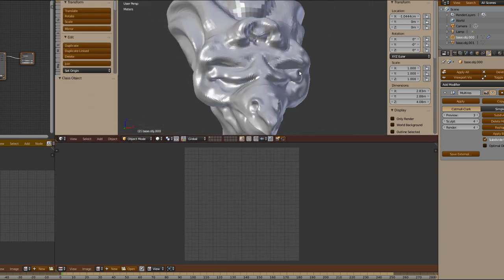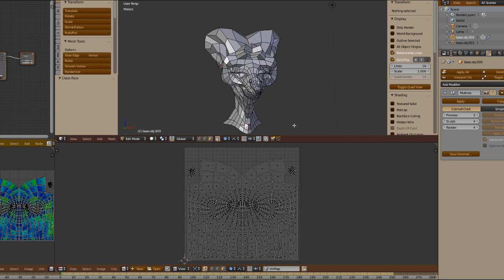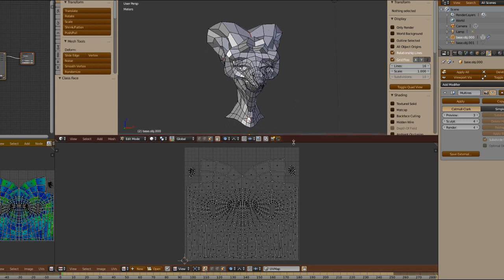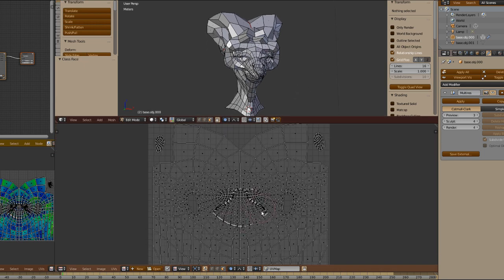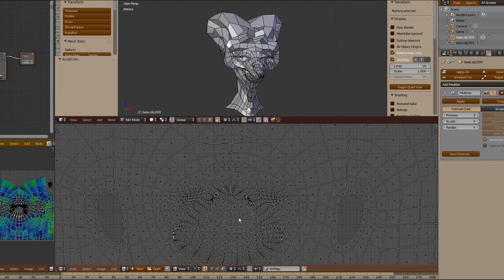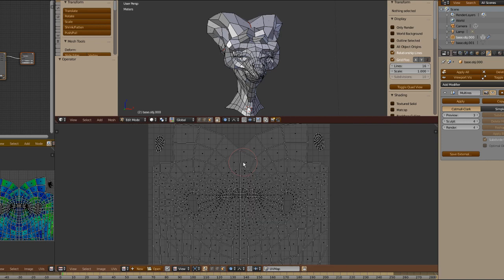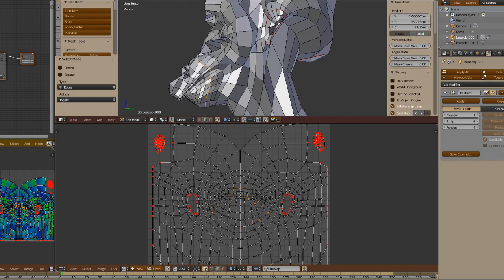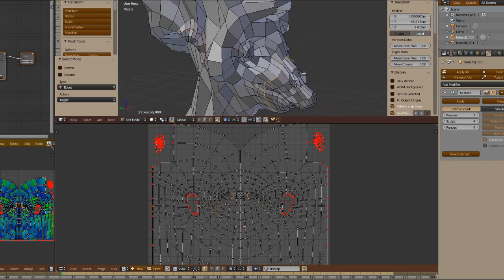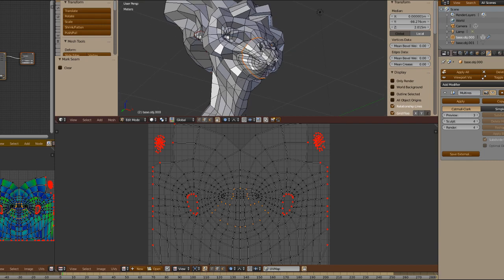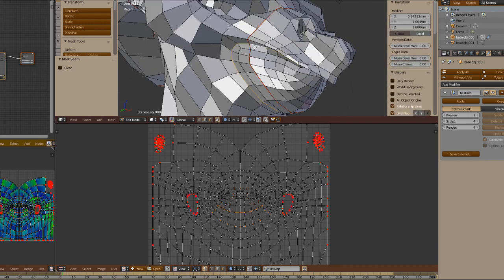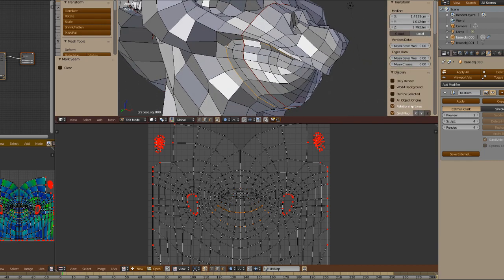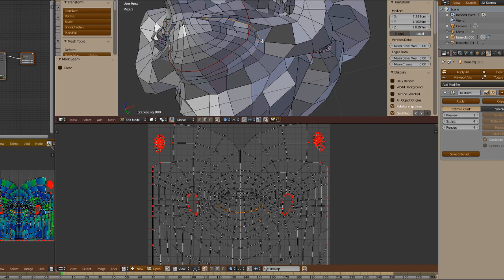Now, I want to make a very important observation. With all these modifications to the structure of the mesh through edit mode with the modeling tools, nothing in the project is broken. If by chance the mesh has UVs and I change the structure of this mesh, as you can see, these changes are automatically propagated to the UVs. The only thing the user has to be aware of is when adding new geometry through the extrude tool. These newly generated geometries will be located above the others in the UVs.